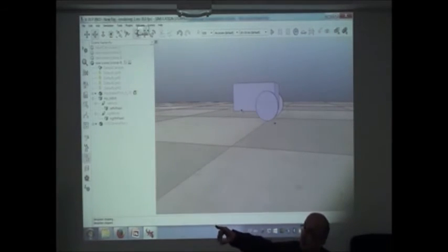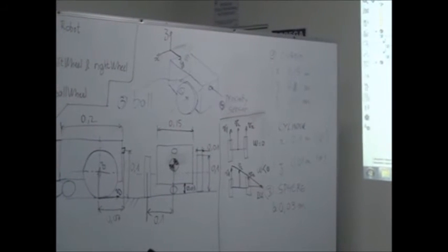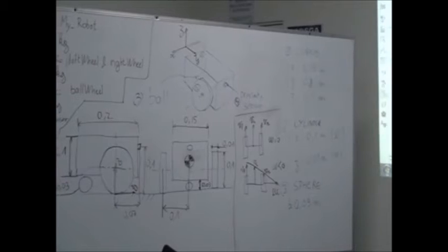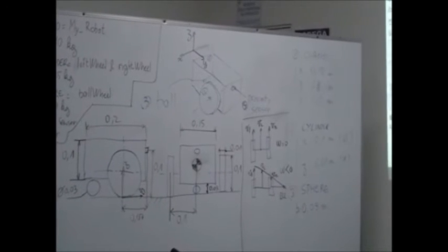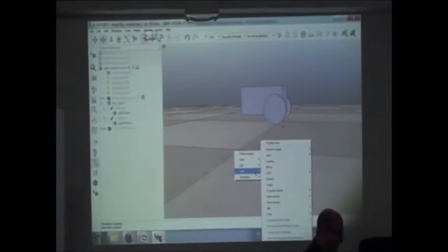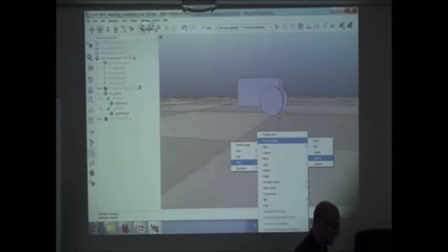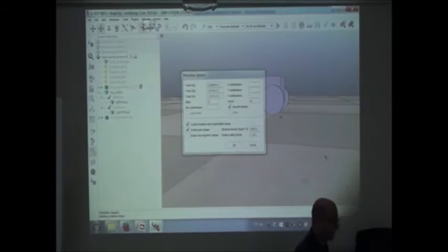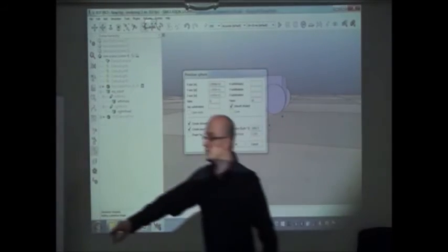So we're going to put a ball, a small ball, a rolling ball, just to have a third point of contact to have the triangle of sustentation. It's called. Okay. So let's do a ball. A ball is like right click, add primitive shapes, and sphere. Okay.